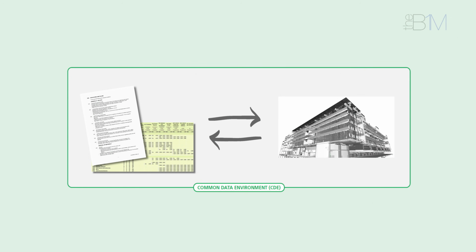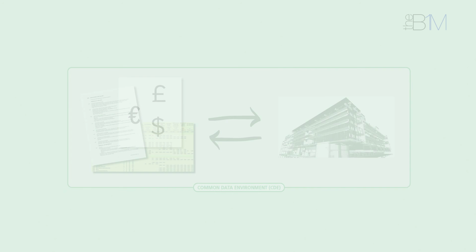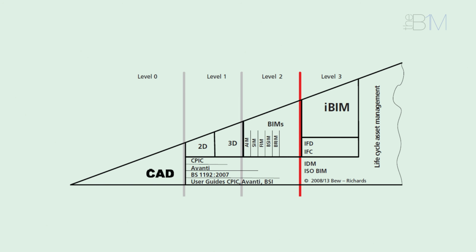One important point to note is that 5D BIM refers to a particular way of linking data to an information model, an additional dimension, if you like, of data. It's quite different to the BIM maturity levels that run from 0 to 3 and beyond, describing the supply chain's ability to exchange information in a digital way. 4D, 5D and even 6D considerations can all occur within BIM level 2. If you're working with 5D BIM, it would be wrong to say that you're working at BIM level 5.